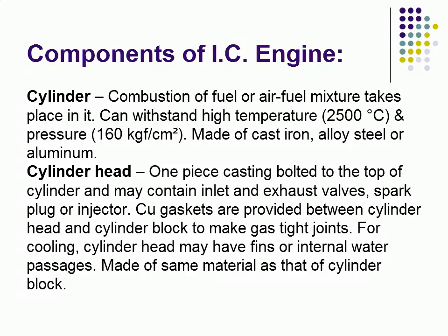The second important component is the cylinder head. It is one piece casting bolted to the top of cylinder and may contain inlet and exhaust valves, spark plug or injector. Copper gaskets are provided between cylinder head and cylinder block to make gas tight joints. For cooling, cylinder head may have fins or internal water passages made of same material as that of cylinder block.